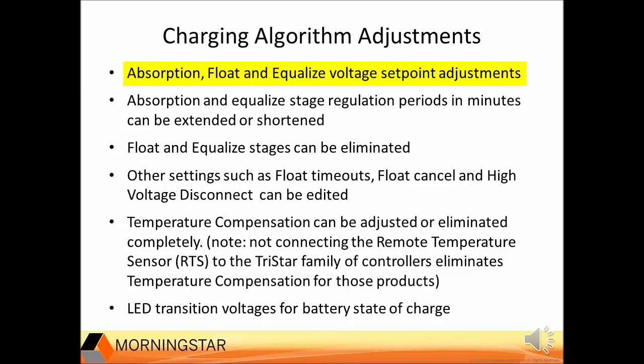So for example, if you're programming it for 36 volt batteries, you would take a multiple of 36. If you're programming it with the 48 volt multiplier of 4, you would set it up with 9 volt nominal to get the 36 volts. 4 times 9 is the 36 volt setting.